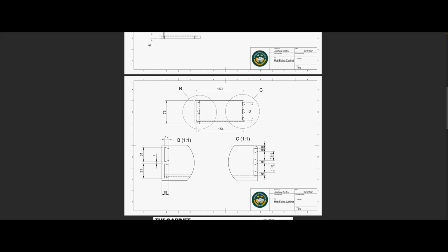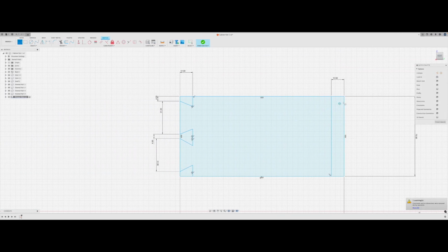It slides in from the rear underneath this backwards piece into slots, which just means you can actually pull it in and out once your drawer is glued together. Which is a very traditional way of building drawers. So you can actually pull them out and adjust them and replace things later as well. So it'll make sense once you see it assembled, but that's why it looks a bit funny and they're not all full dovetails.